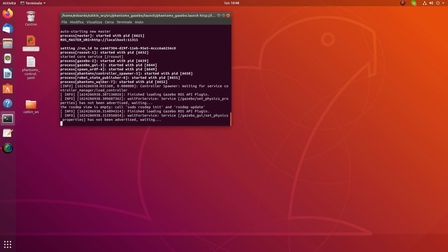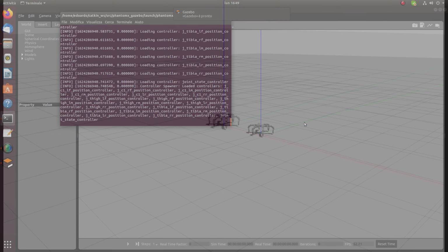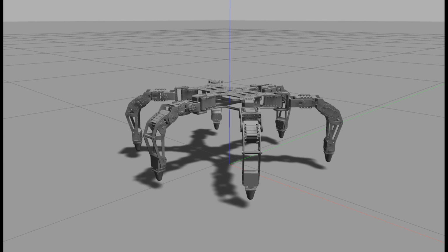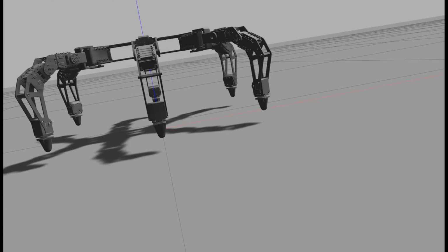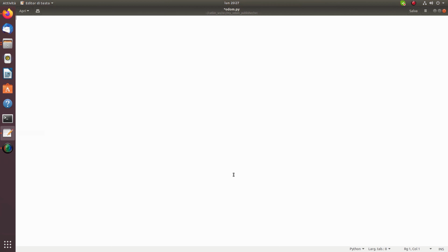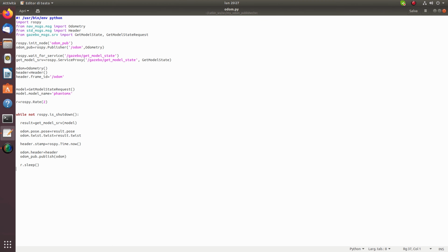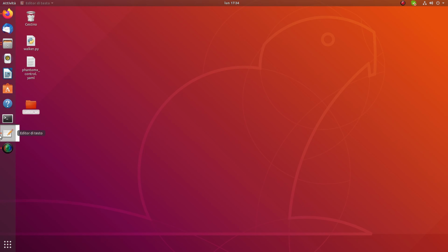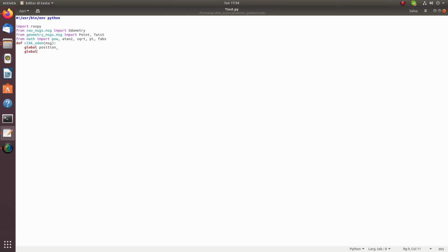Now we have all the elements to launch the Gazebo simulation. However, at this level, to move the hexapod, the presence of the user is still necessary. So the next step is to make the robot capable of moving to a preset position. To achieve this task, it is necessary to implement a node that publishes and updates the position when the robot is moving towards the goal point.